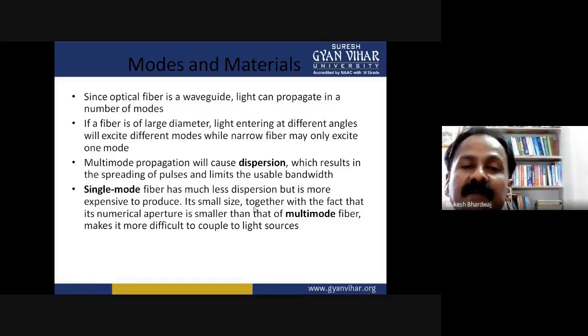Multimode graded index fibers tend to have a smaller core diameter than multimode step index fiber. Although overall diameter including the buffer jacket is usually about the same, the typical structure is illustrated. That is, core diameter is 30 to 100 micrometer, clad diameter is 100 to 150 micrometer, and the attenuation is 2 to 10 dB per kilometer at the wavelength of 0.85 micrometer, with generally a scattering limit.